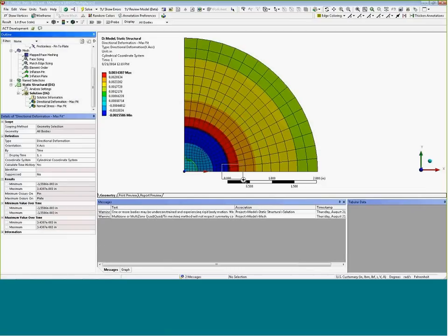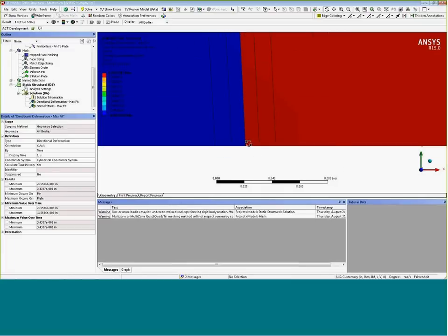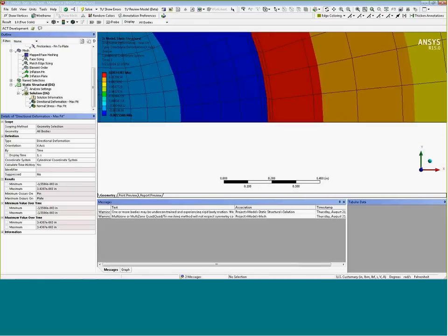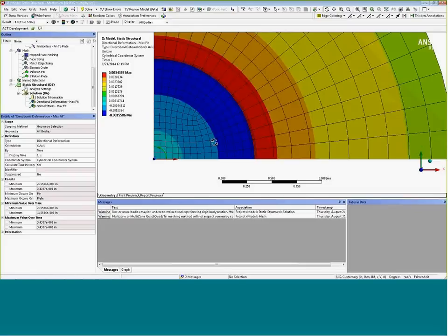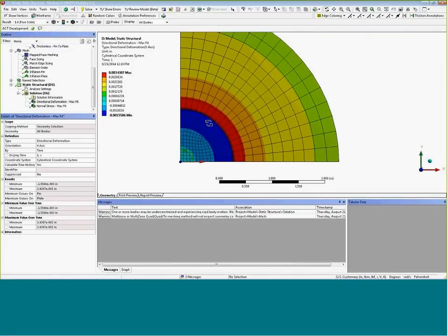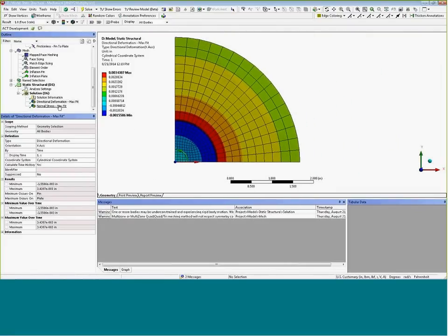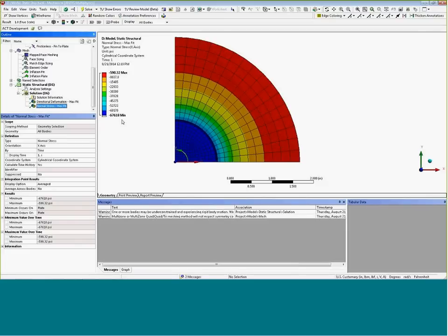And if we zoom in down at this location again, we see that we no longer see that physical gap in there. The surfaces are touching line on line because we didn't offset the contact surface amount. So this is maybe a more realistic answer. Let's say the pin is modeled with its true diameter, it's modeled line on line, looks a little nicer. Results are a little bit more accurate, but really it didn't make any difference how we modeled this in either approach. They're both essentially the same answer.